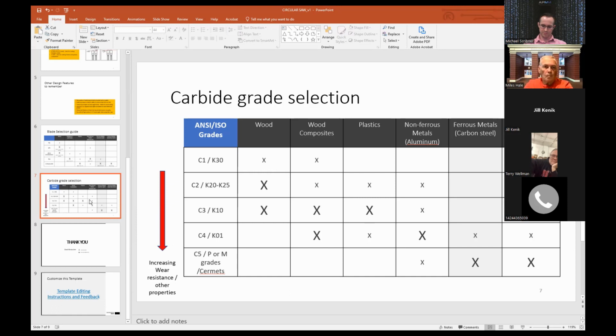Really primarily, I think, for fine woodworking, generally trim work, other things of that nature that you'll see. Again, because of the hardness and the wear resistance of that carbide, if you are cutting and you happen to hit a metallic structure, it's not going to damage the carbide generally. So really good grade, most versatile, I'd say.